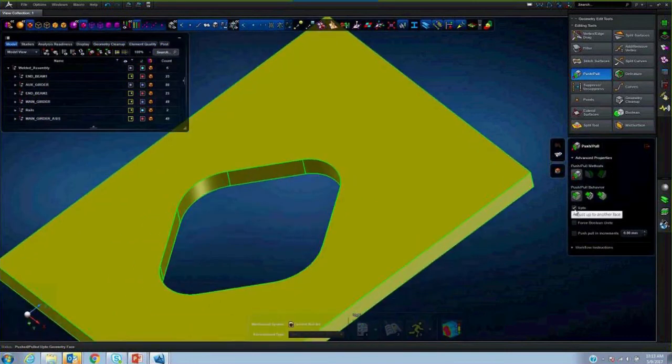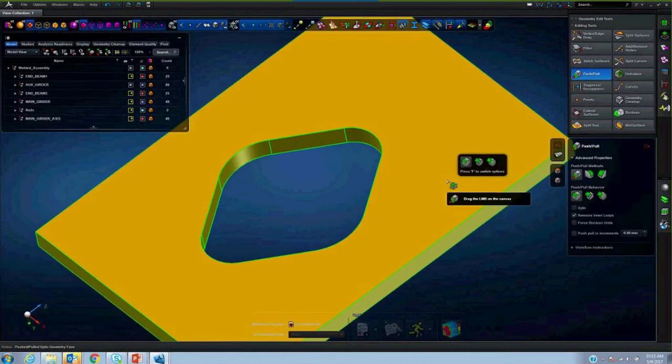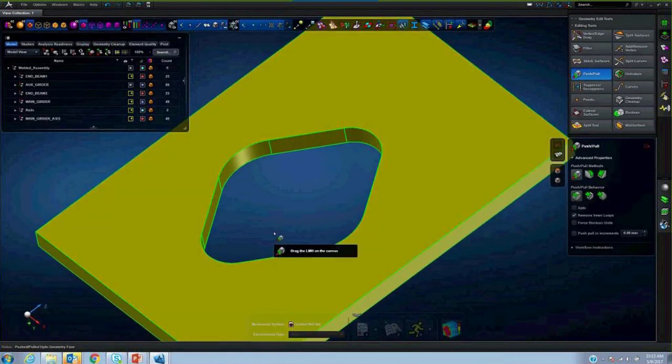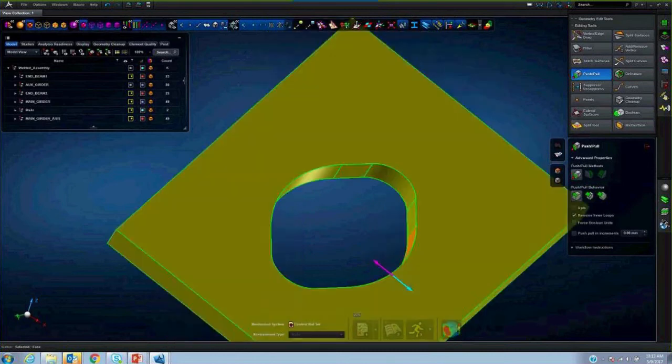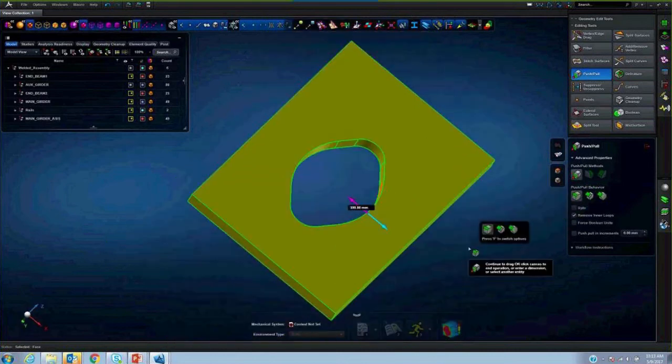Can I make some design changes? For example, if I would like to change the size of this hole, I can take the face, and right now that diameter is about 150. If I make it 300, now you see how the geometry gets modified. Likewise, if I want to make it kind of symmetric, let's make the change that easy. So that's how the direct modeler that's built inside Apex will let you clean the geometry, at the same time modify the geometry.